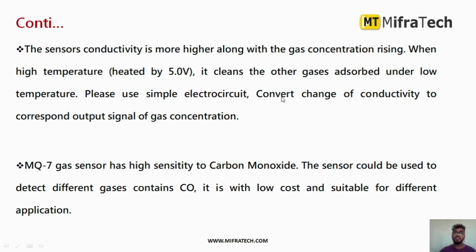When the temperature is high, it cleans the other gases absorbed under the low temperature. The MQ7 gas sensor has high sensitivity to carbon monoxide, a combustible gas, and it can be used to detect different gases which also contain carbon monoxide. It is very low cost and suitable for different applications.